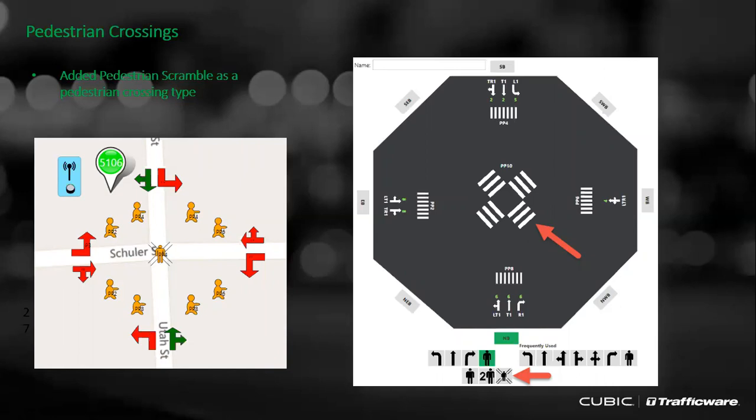You can program that by working the controller directly or through ATMS, but that is not defined through the intersection layout. So basically, you specify that the detector number N will collect volumes only when phase number, let's say 6, is green or yellow, and that is handled outside of intersection layout.